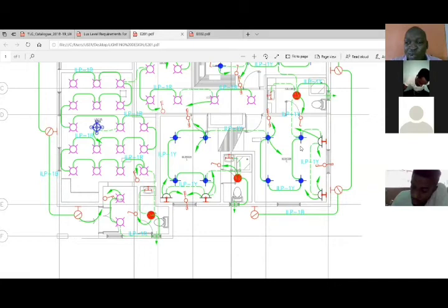Go back to our formula of room index. I gave you our length to be 4 meters, our width to be 3 meters. Can we then allow your headroom to be 3 meters? Yes. So you can take that to be 3 meters. Substitute this factor into the value for the room index, which is K equals L multiplied by W all over L plus W multiplied by the headroom, which is 3 meters now. What does it give us? Anybody?